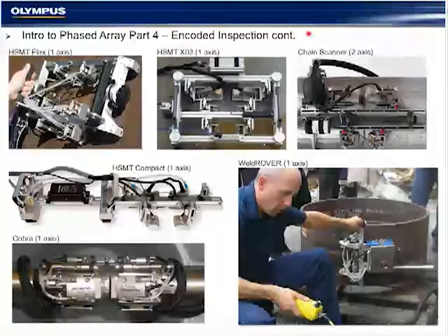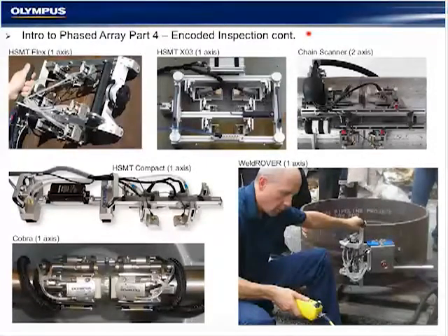All of the scanners can be repositioned, reconfigured. The probes can be moved in several different positions and orientations. Some allow the wheels to be rotated, like the X03 for parallel scanning alongside the weld.